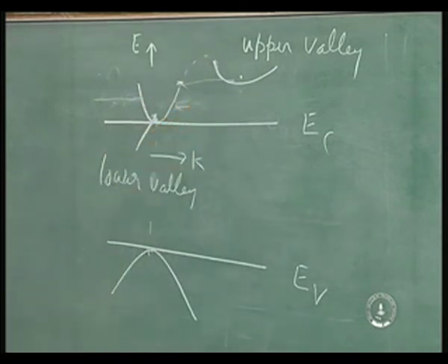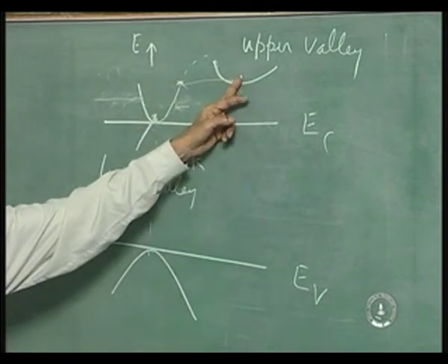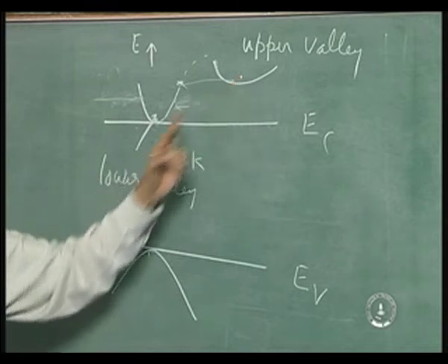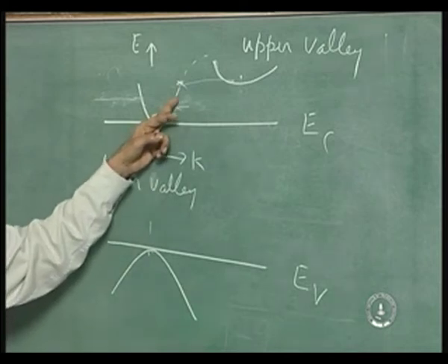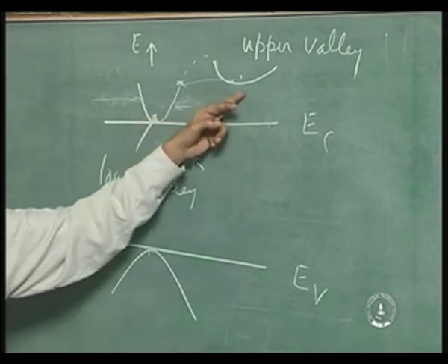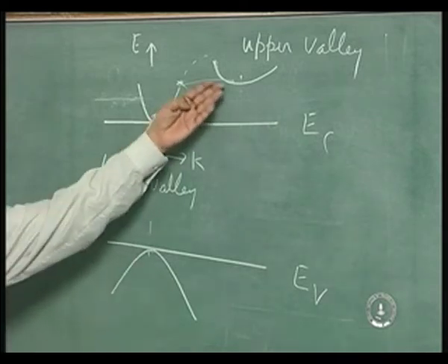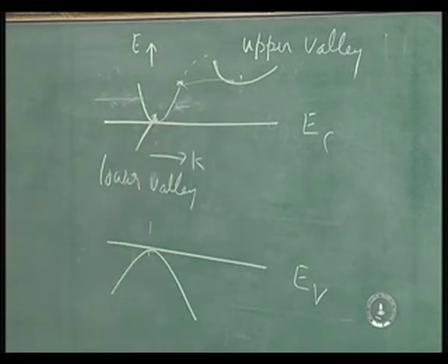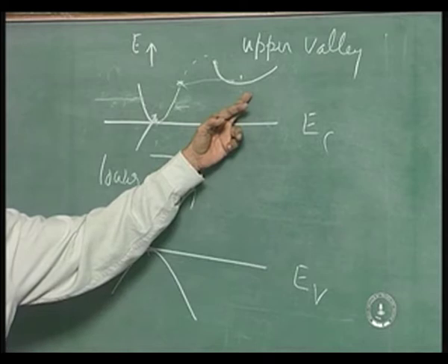In other words, this is a momentum difference, it gains enough momentum, it finds itself in that portion. So, as we keep on increasing the energy, by increase in electric field, velocity keeps on increasing. I have talked about one electron getting transferred there, that electron will find itself having a lower velocity. All the 100,000 electrons will not get transferred onto that simultaneously. This is a sort of probability. So, many of them will get transferred as we keep on increasing energy. Finally, if all these electrons have got transferred onto that, the effective velocity of those will be smaller.